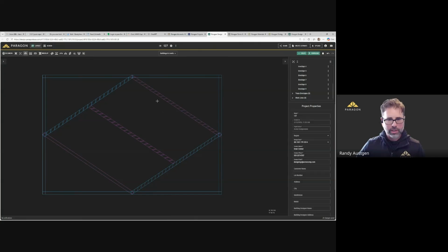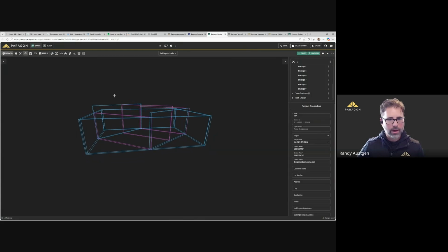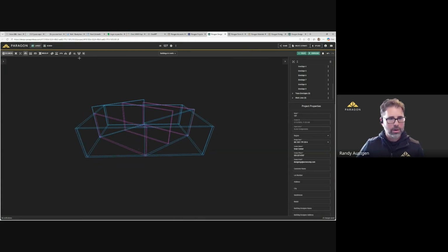And so we can see a different hatch pattern is defined based on the different wall elevations. So kind of that top of wall. If we want to see what this looks like, here we are. And then while we're in 3D, I'm going to go ahead and get us into our different view options. All right. So we saw hatched, and hatch only is kind of only the hatching is only displayed while you're in that 2D view.